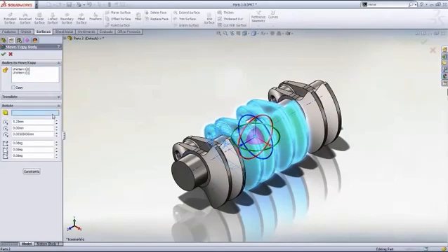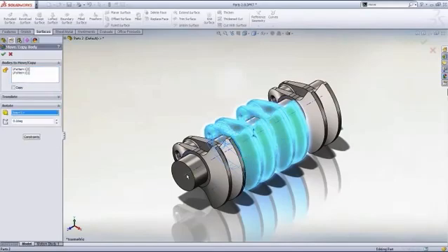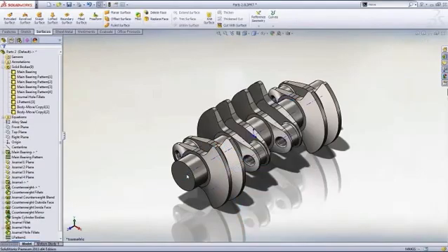To rotate about a specific axis, we're again going to utilize the temporary axes SolidWorks created for us. Then we just need to specify the rotation angle, which is 180 degrees. When you're finished with the temporary axes, you can also simply toggle them back off using the same pull down. That's something I really like about them. Not only do I not have to create them, I can show them when I want and turn them off when I don't need them.